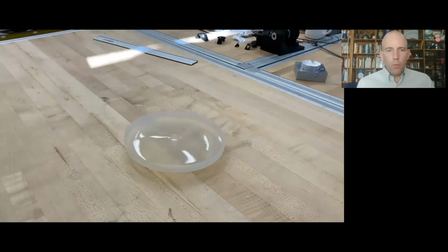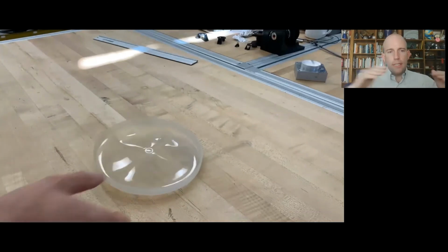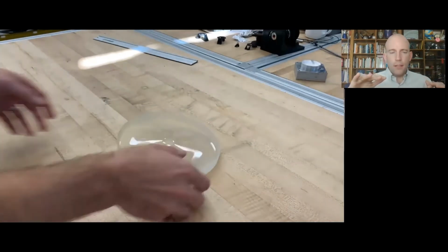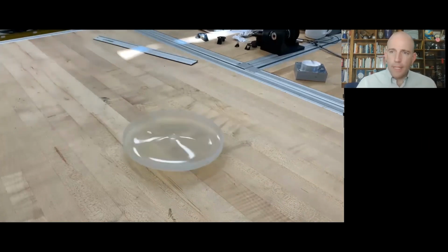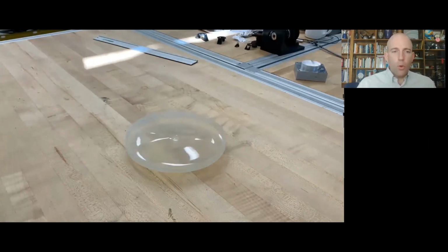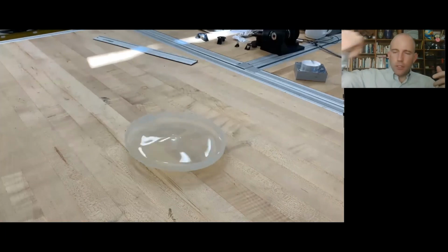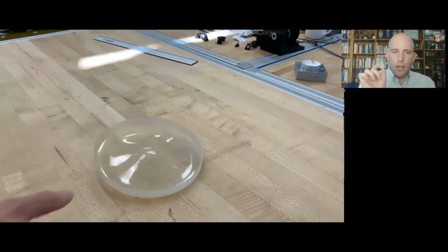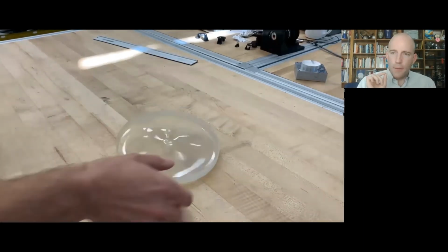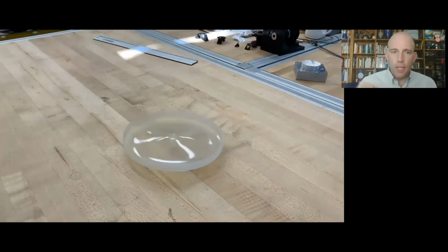One of the big contributors to this is that when you're trying to slide it across the table, the displacement of the main inertia is the same as the displacement of the contact point. Whereas when you spin it, you have a big rotational inertia but a very small radius for the friction to act at the contact patch about the center of rotation.